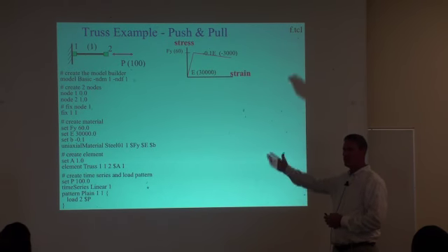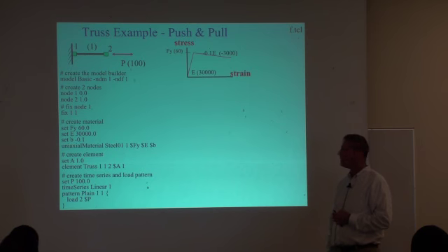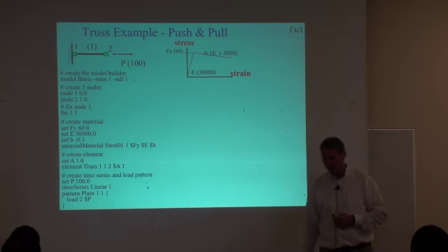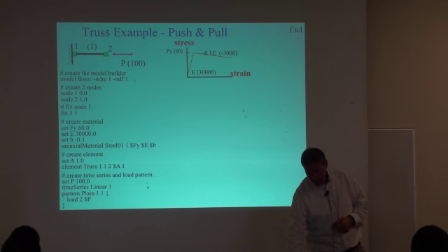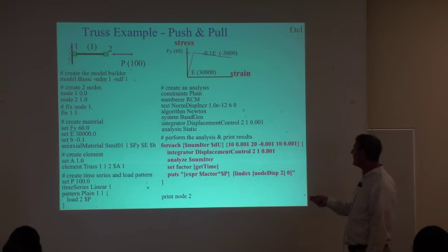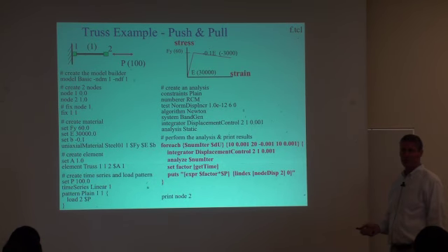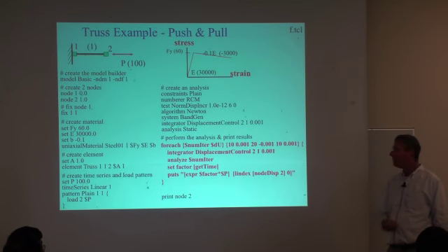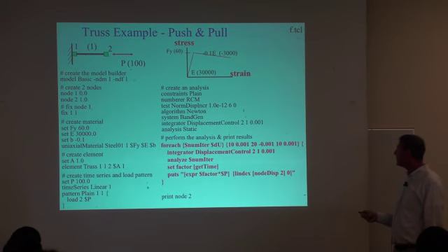So the model is identical to what we just had. We still have that truss, two nodes, boundary condition, and an applied load. We construct our static analysis as before. And now, instead of analyze 10, we're changing what's going on in the analysis. We're using the foreach command that we saw in my slides from the previous presentation, the basic Tcl command. So here's the foreach.